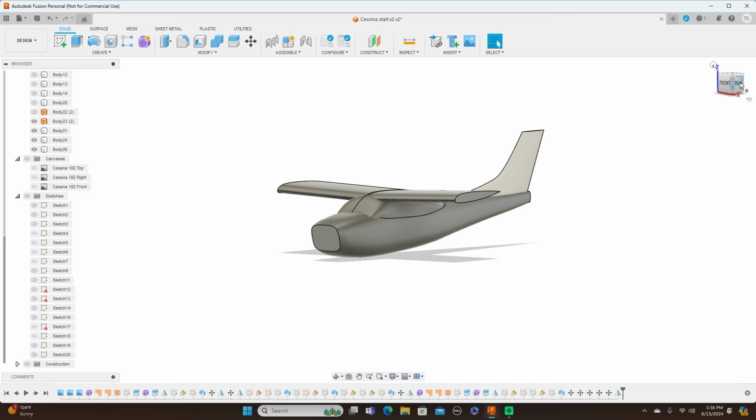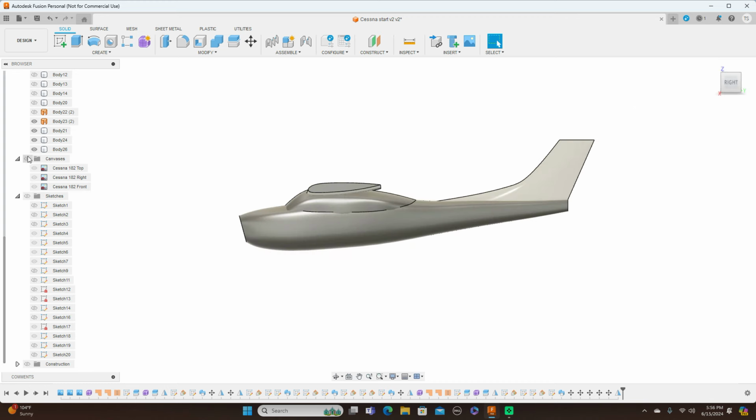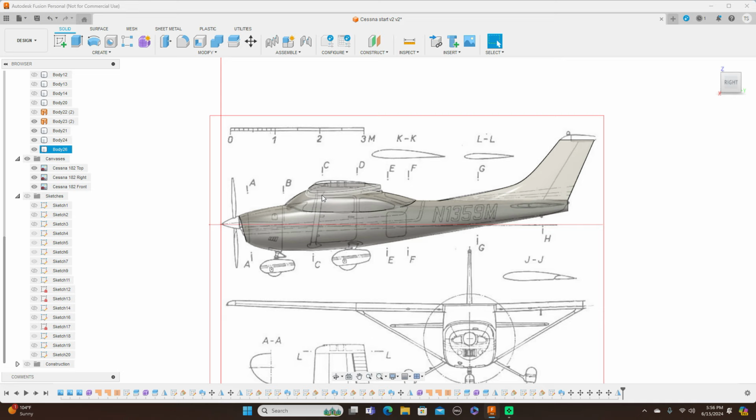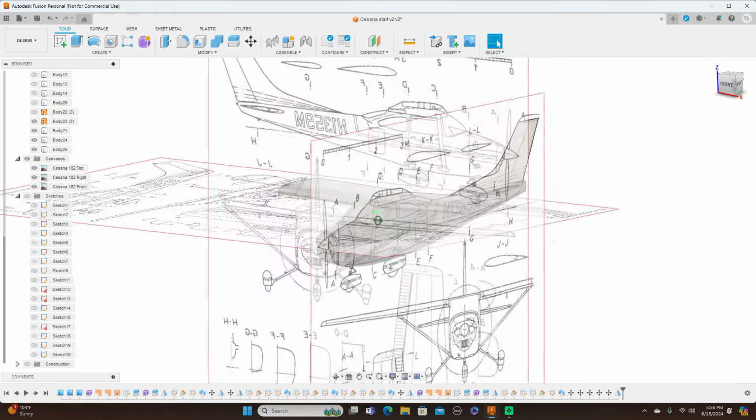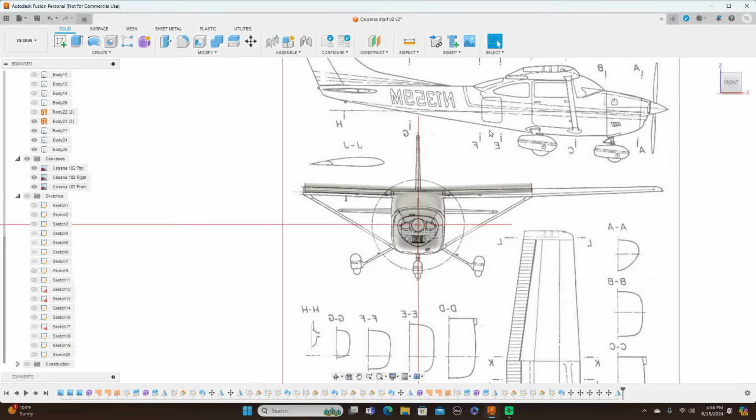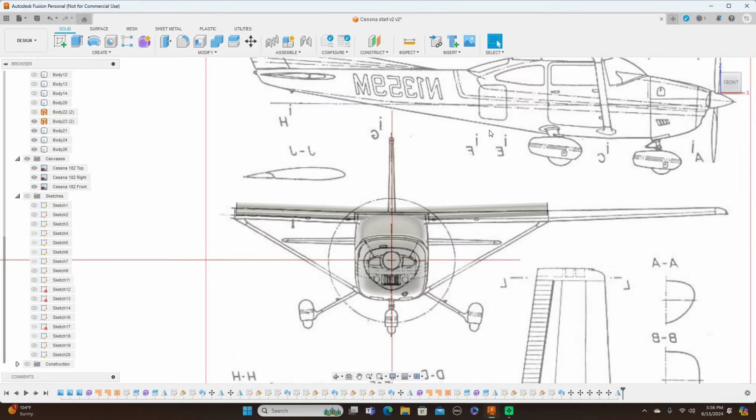And if you're wondering about these here, now there are various ways you can do those. You can draw it on this plane, just draw this outside square here, and then extrude that, and just move it back to where it needs to be on the side here. That's one way.